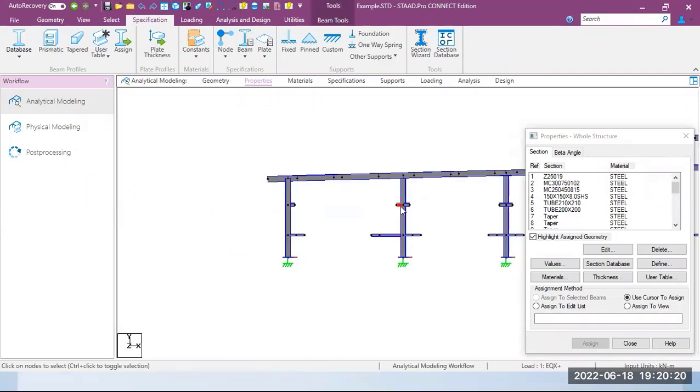All these connections, this bracket connection, will have a moment connection or rigid connection with this column. This platform cantilever beam also will have moment connections with these columns, and this frame rafter will also have a moment connection with these members. And these are the rigid connections.